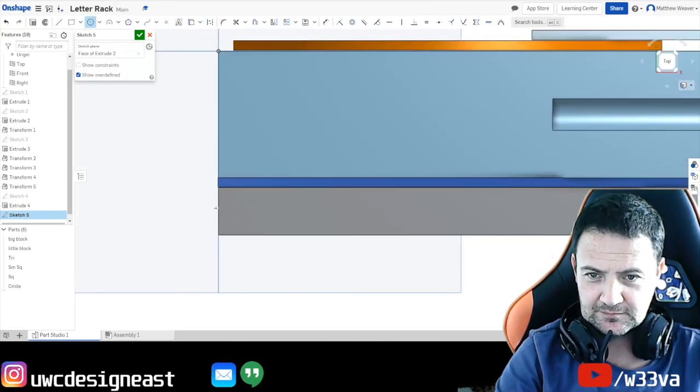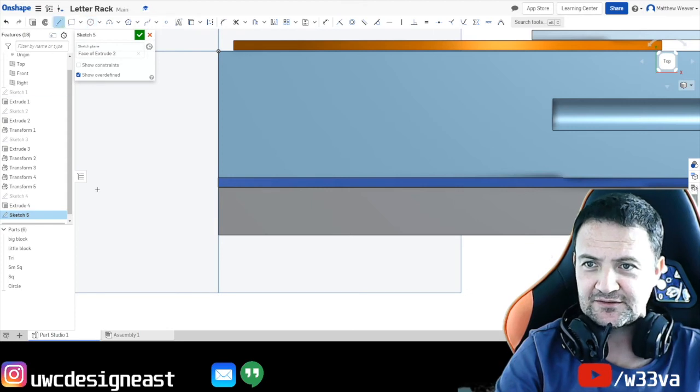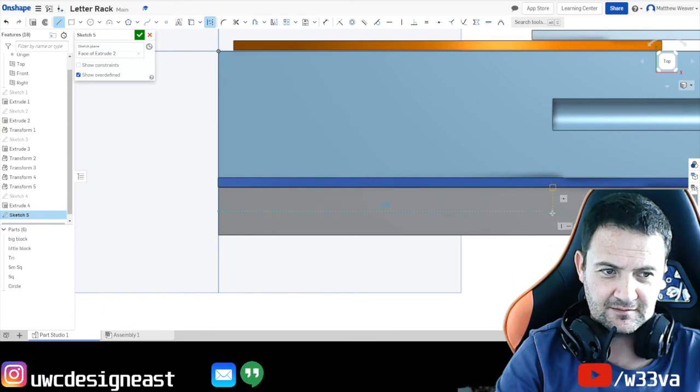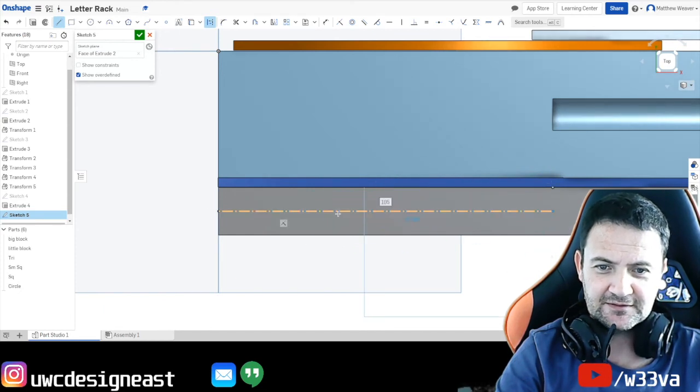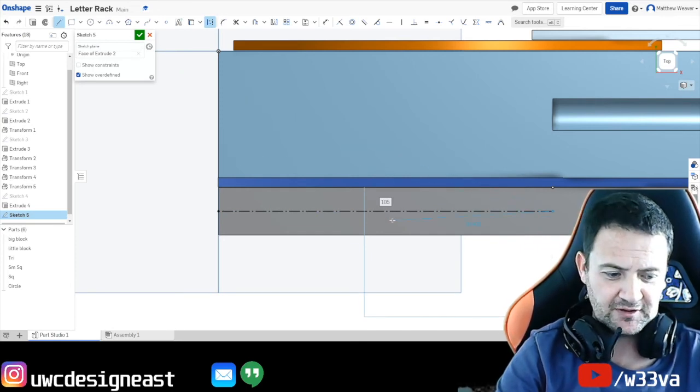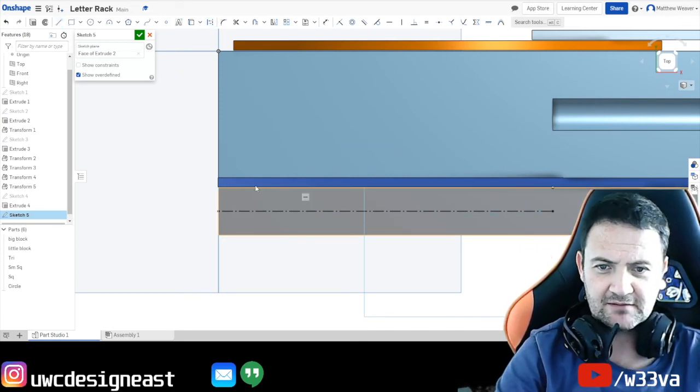Circle. I'll tell you what, let's do a line. Now here, do you remember construction lines? Can you see that dotted line? Let's turn this. You see construction? Go to there, click there. There's your halfway point. Can you see the dotted line? That's the construction line. Okay, so that's pretty good. Let's escape that. We'll get rid of that.